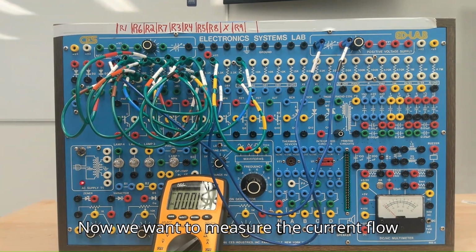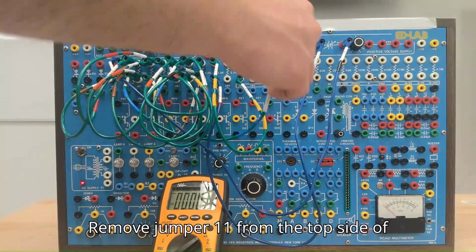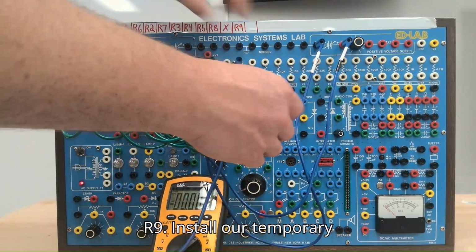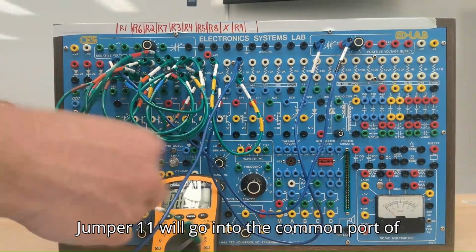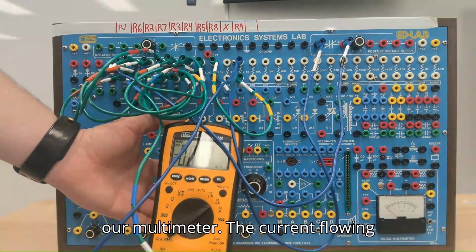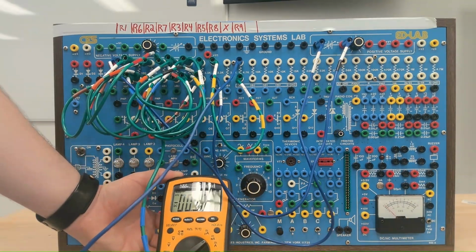Now we want to measure the current flow through J11. Remove jumper 11 from the top side of R9. Install our temporary test lead into the top side of R9. Jumper 11 will go into the common port of our multimeter. The current flowing through J11, 0.5 milliamps.